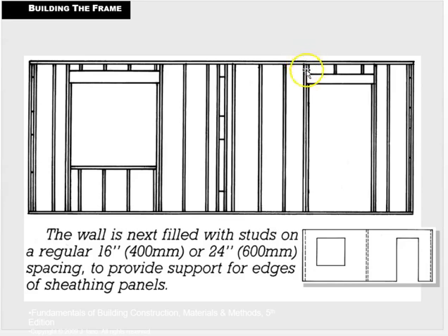This probably falls on the 16-inch increment, and then we keep going. 16, 16, 16 here, 16, and so on, all the way across. And that's so that the plywood, the 4x8 sheets of plywood, when they arrive, and the 4x8 sheets of drywall when they arrive, they'll have fastening, and the carpenters installing them will have the fastening members that they need.